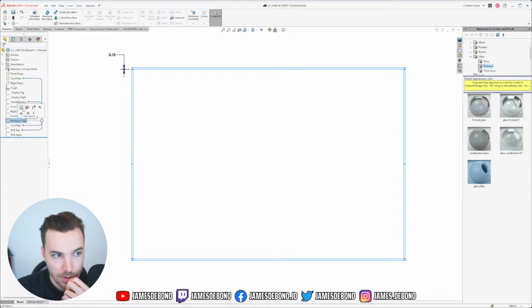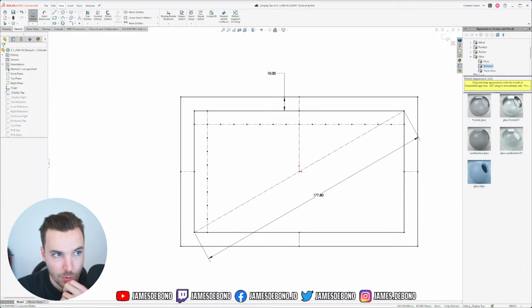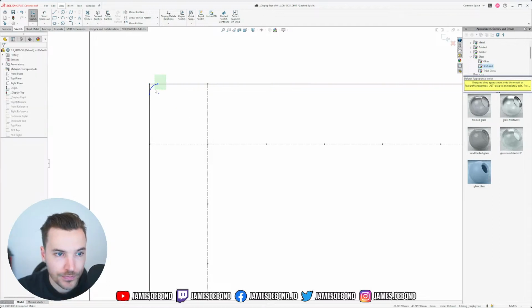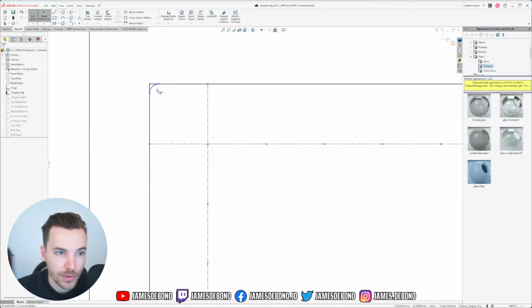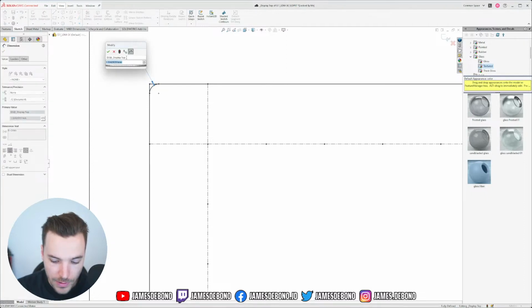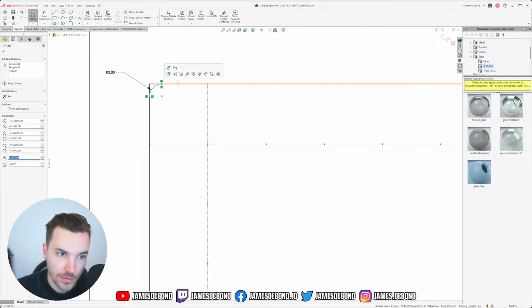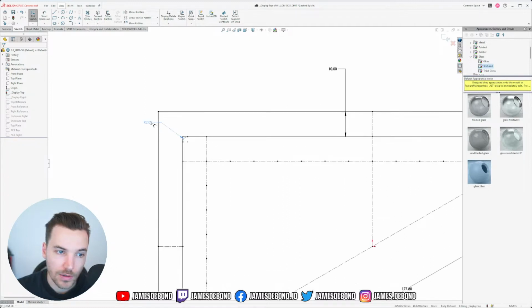I might add corner radiuses onto here. Do I want corner radiuses? I'm just going to do one, because the hole in the top of the device should have radiuses in the corners. As in, the hole in the metal that looks through into the display should have radiused corners.